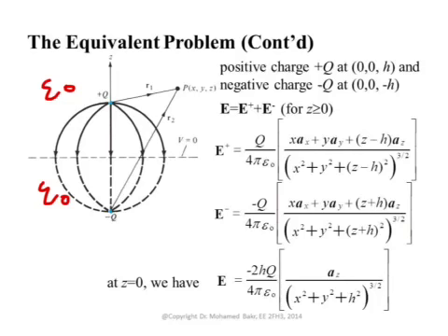Okay. Now, if you want to get the charge density, we agreed from the boundary conditions that we discussed earlier that the normal component of D, normal to any conductor, will give you the surface charge density at this point. So we simply multiply this component by epsilon naught, and this will give us the surface charge density. Of course, surface charge density must be negative, because this is a positive charge, and this positive charge will induce negative charges on the ground plane.